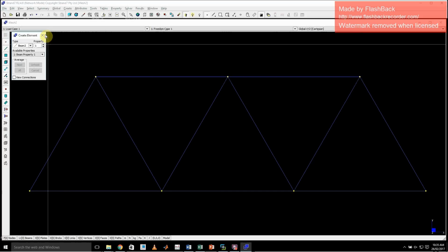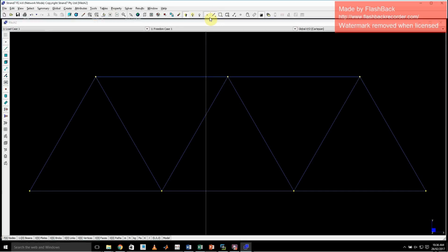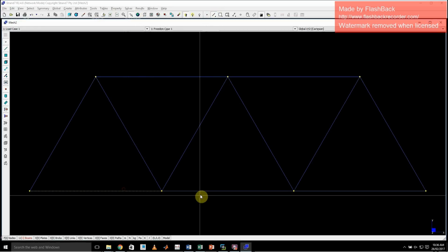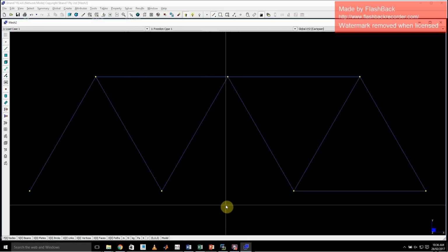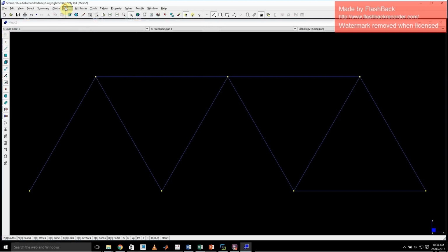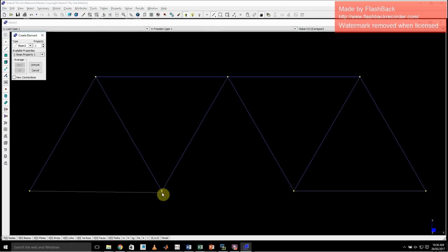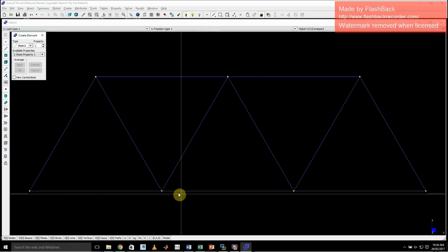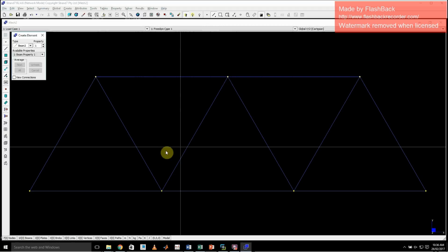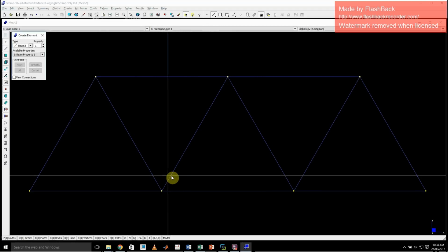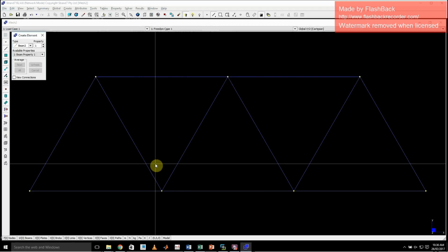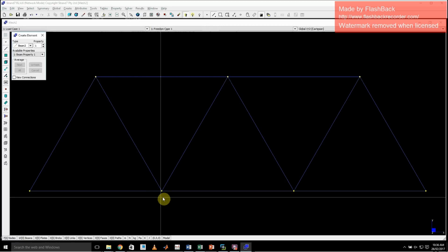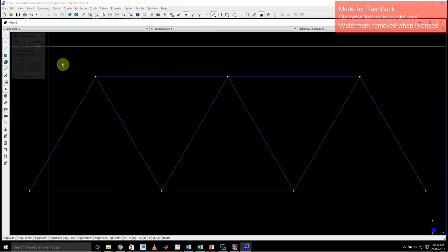One thing that, again, I will talk about in a later video, but I just want to show you something very quickly. If I was to delete these two, and create another beam that went from here all the way to here, not joining to this one first, just going straight through, that beam is not actually connected to these two beams at all, okay? It doesn't work that way. If you want a connection point, you need to split your beam up, all right?